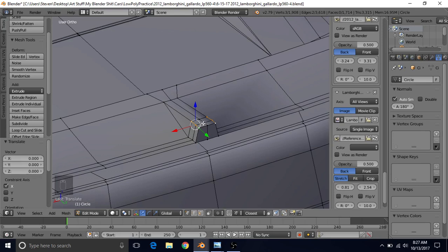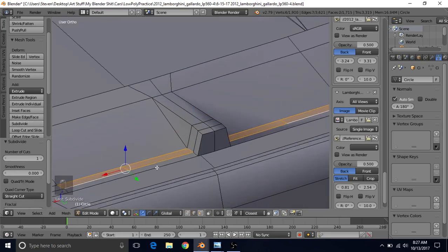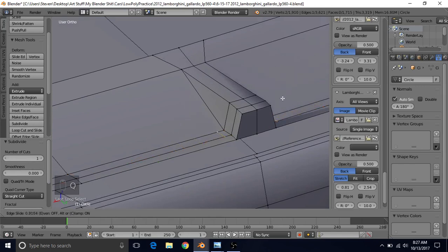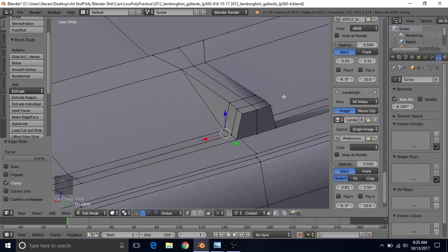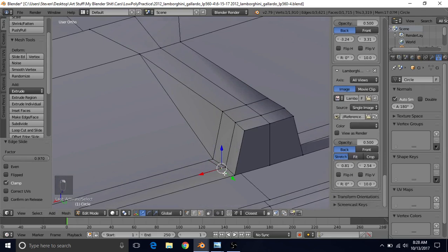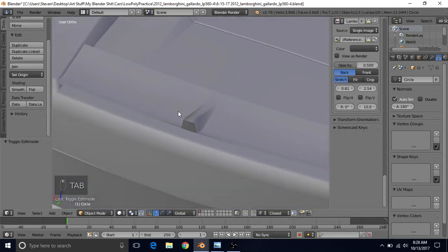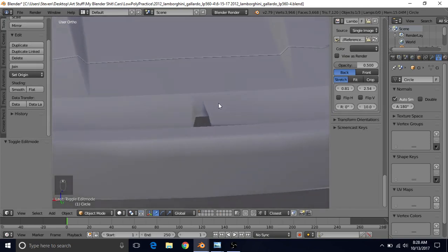Now that we're getting this shading issue, to fix that, we're going to go to Edge Select and select these two edges, do Subdivide, switch to Vertex Select, Alt right click here to get this newly created edge, press Q to slide, and then just like we've done before, we're going to join these at the top and bottom, and that will help to correct any shading issues we have here.